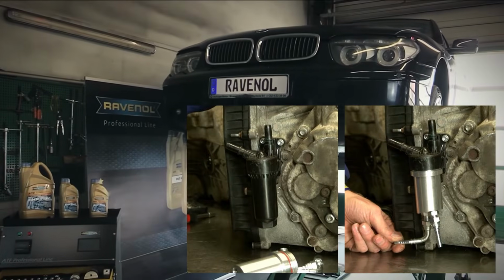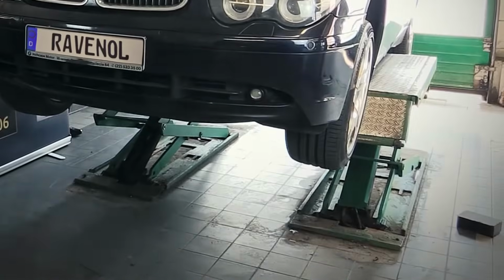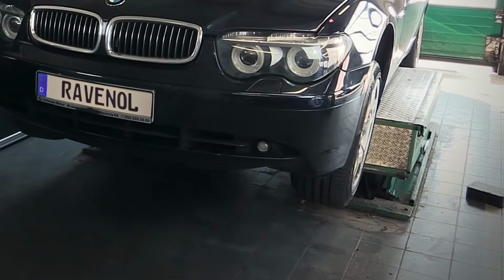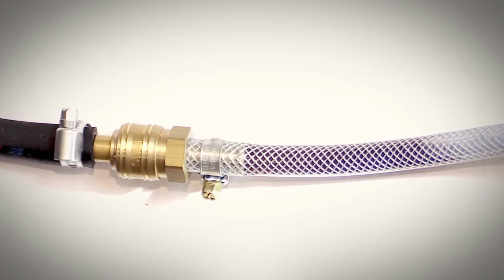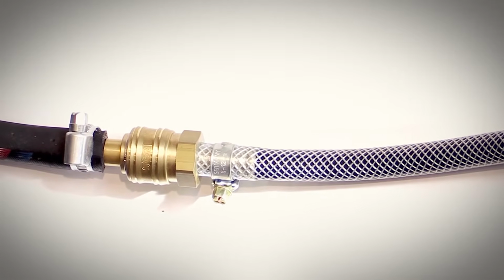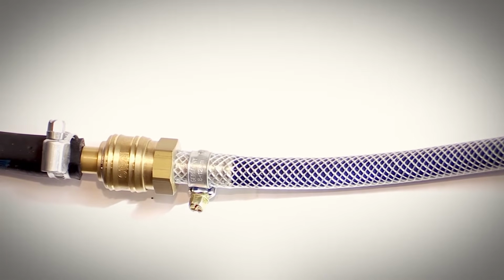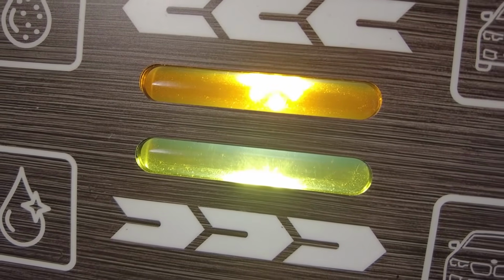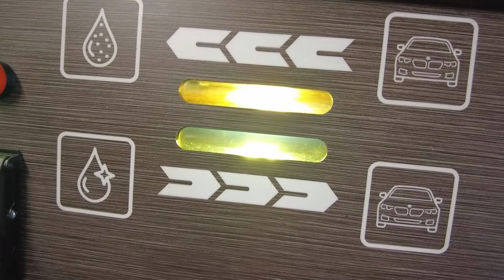After connecting the device, check that the direction of flow of the ATF transmission fluid is correct. Also, start the car's engine, and note the direction of flow of the ATF Professional Line 2 device in the sight glass. Air bubbles that are visible for a short time should flow in the direction indicated. The new device has a clear sight glass. The oil must flow from the vehicle to the device in the same direction as the arrow above the sight glass. Only this direction of flow through the device is correct.